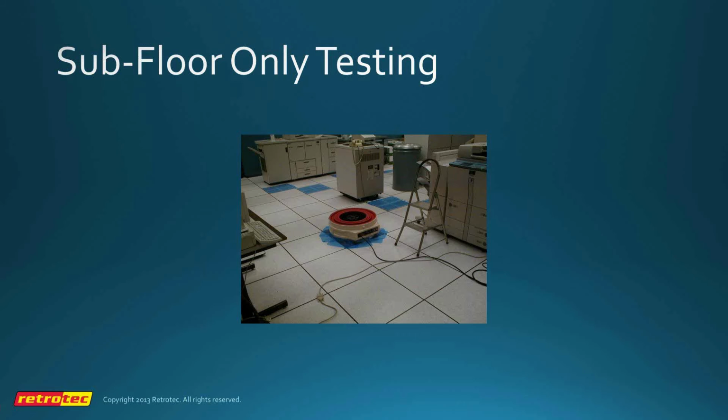The other way that this can be utilized is that we can effectively measure the lower leak in the enclosure by measuring the leakage below the subfloor. We can then measure the room leaks and come to some conclusions about where the leaks are in the room, and we can utilize this for both ISO and NFPA for determining the location of the leaks and coming up with a value of F. I don't want to get into that in a lot of detail. If you have a situation like this that comes up, we usually walk through it with our tech support and get it sorted out.